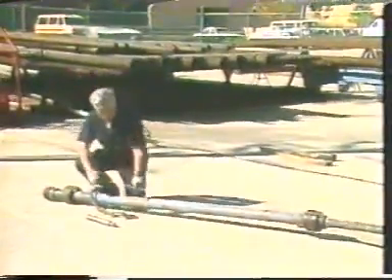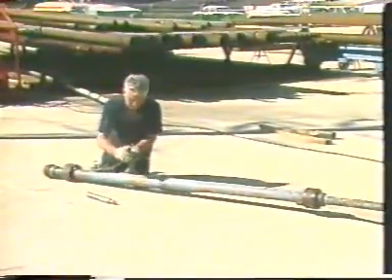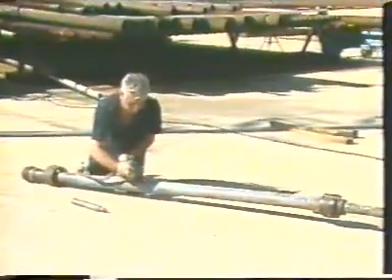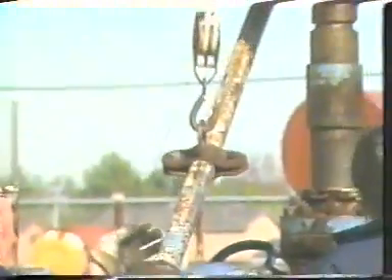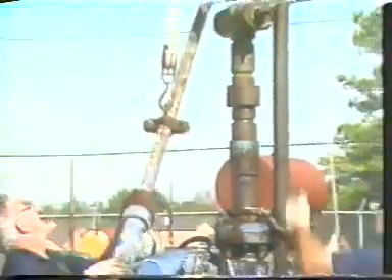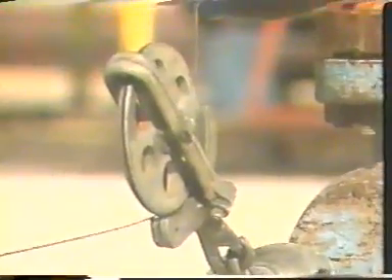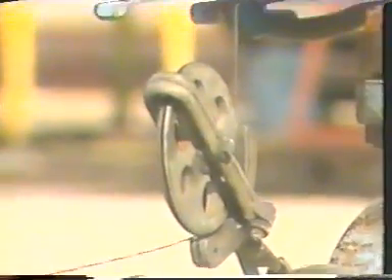Before the lubricator can be lifted into position on the wellhead, the tool string must be secured in the lubricator so it cannot fall out while the lubricator is being lifted. The wire is clamped to the lubricator with a wireline clamp. Next, the lubricator is lifted into position above the wellhead with the rope falls. A sheave is attached to the tree, and the wireline is threaded through this sheave. The slack left in the wireline is reeled onto the reel of the wireline unit, and the clamp is removed from the wire.